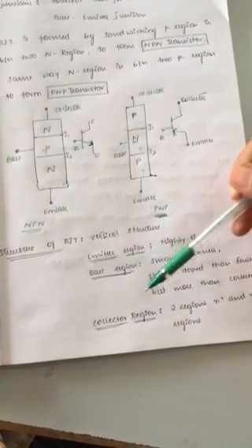So it is having three regions as per the three terminals, that is an emitter, base and the collector. So we are having the three layer region. In an emitter region, the emitter must be highly doped, whereas the base layer must be smaller in thickness when compared to the emitter and the collector, but it must be lightly doped, more lightly doped when compared to an emitter, and a bit more when compared to the collector.